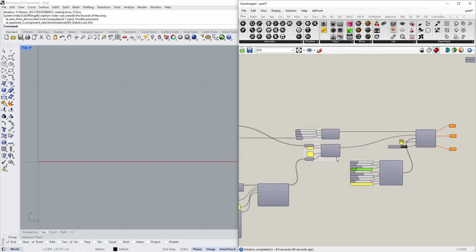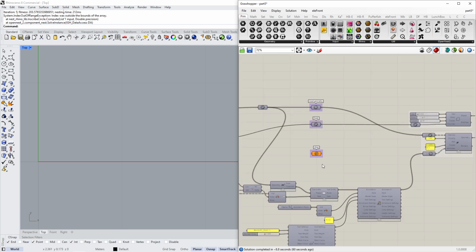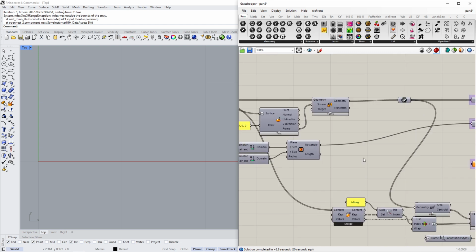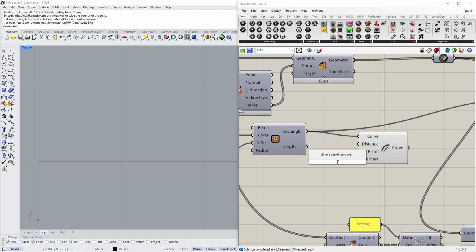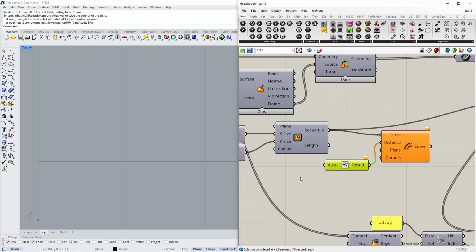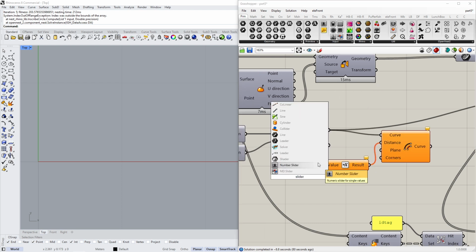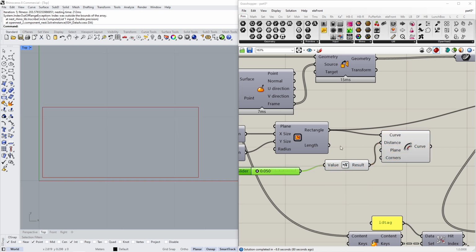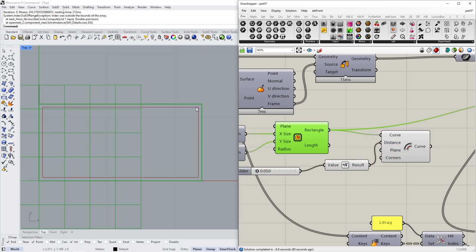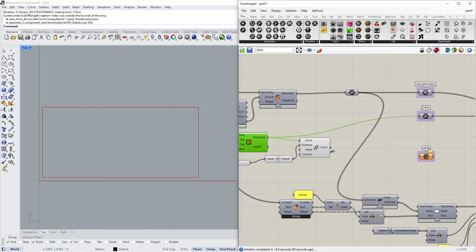So usually you also want to have a little bit of space there. So the way to remedy that is to offset the sheet before you insert it, with a small number. So let's say also 0.05. So I offset the rectangle to the inside. So we used this one instead of the outside one as our sheet.